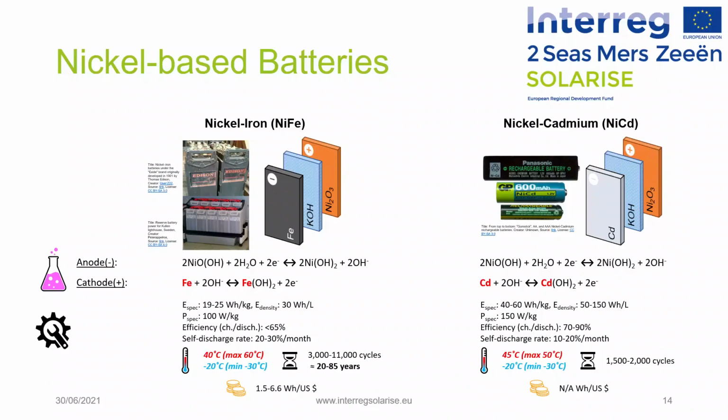However, the materials are more expensive than those of the lead-acid battery and the cells have high self-discharge rates. In addition, nickel metal hydride and lithium-ion batteries have recently become commercially available and less expensive, with the former type now rivaling nickel-cadmium batteries in cost. Where energy density is important, nickel-cadmium batteries are now at a disadvantage compared to nickel metal hydride or lithium-ion batteries.